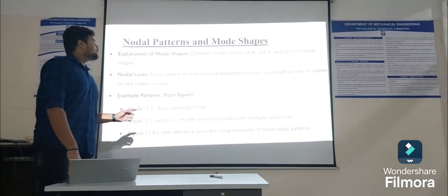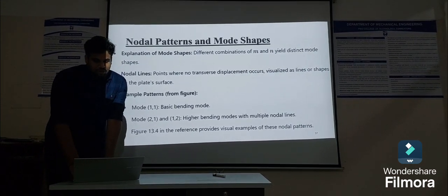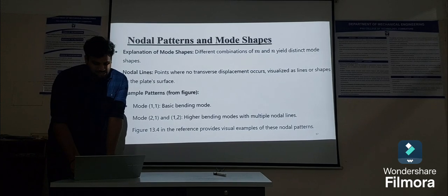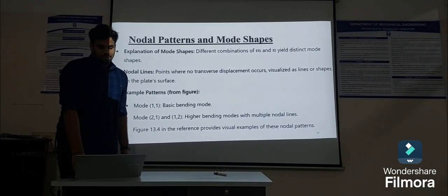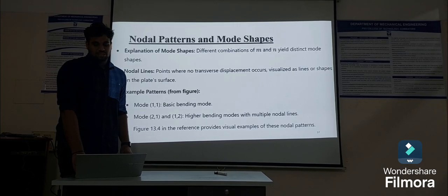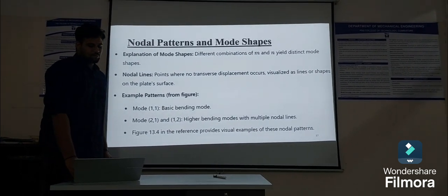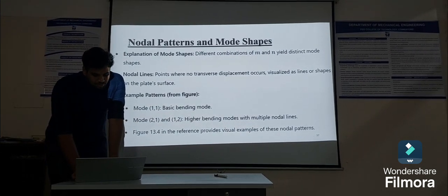Nodal patterns and mode shapes. Explanation of nodal shapes. Different combinations of m and n yield different distinct mode shapes. Nodal lines are points where no transverse displacement occurs, visualized as lines or shapes on the plate surface. Example patterns from figures are given.